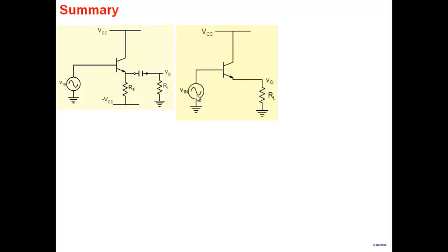And then somebody can very easily reject this and say, well, if the input is very small, obviously the transistor will not conduct. But if the input is large, I have +5 and -5 sinusoidal, well, at least it's going to conduct in the positive cycle. So you say, yes, it's an amplifier which will have 0 standby power, but a lot of distortion. So you go through a phase of what if I bias it, what if I don't bias it at all. So you arrive at an amplifier like this.